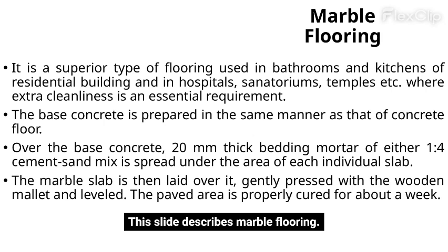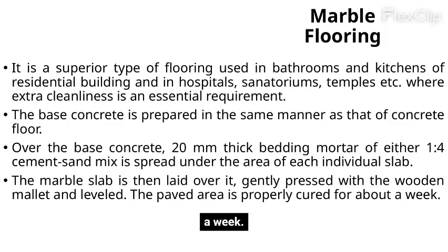This slide describes marble flooring. It's a superior option used in bathrooms, kitchens, hospitals, and temples where cleanliness is essential. The base concrete is prepared as in concrete flooring. A 20 mm bedding mortar is spread under each slab. The marble slab is laid, pressed, and leveled. The paved area is cured for about a week.